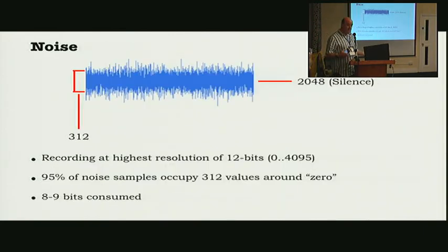So the noise in the device is probably caused by the non-professional hardware. I mean, this is not exactly a sort of professional piece of kit. You do have the ability to, obviously, because you can write out, you can play back pre-recorded audio. And when I've done that, effectively, it's clear that all of the noise is coming from the analog components on the input. But nevertheless, it's really quite noisy and constitutes more than, if this is a 12-bit recording, 8 or 9 bits of it are just consumed by this noise, which in silence regions is really painful.